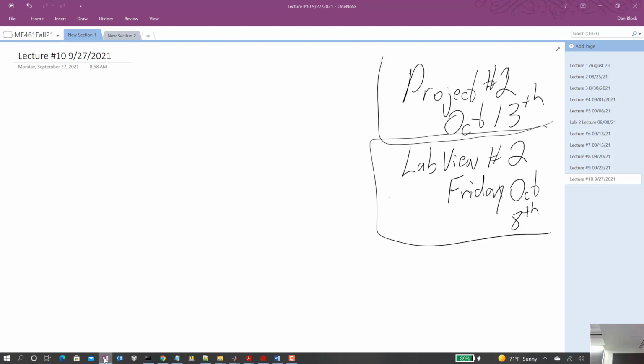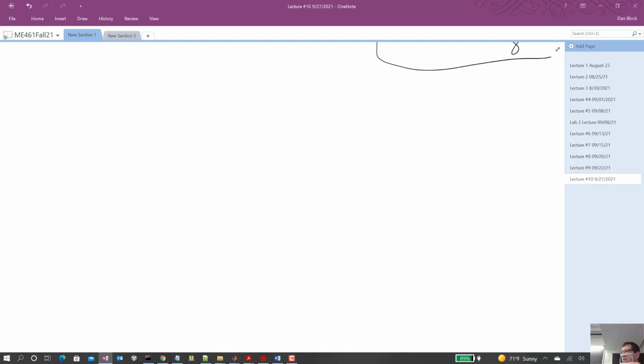So most microcontrollers have 12-bit ADCs, and some have 10-bit, even less resolution. This one has its DAC only 12-bit. Its ADC, the ADCs we're talking about, can actually be set up to be 16-bit. If that sounds like something you'd like to play with in your final project, please tell me. I've never set the 16-bit option. It'd be interesting to see if we can get a little better sampling, less noise and things like that with it. So let's start with the DAC.